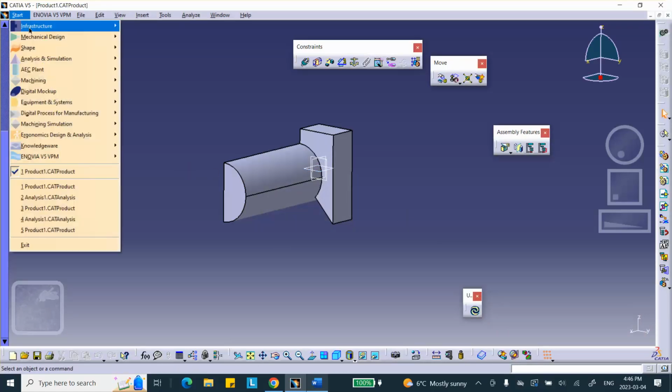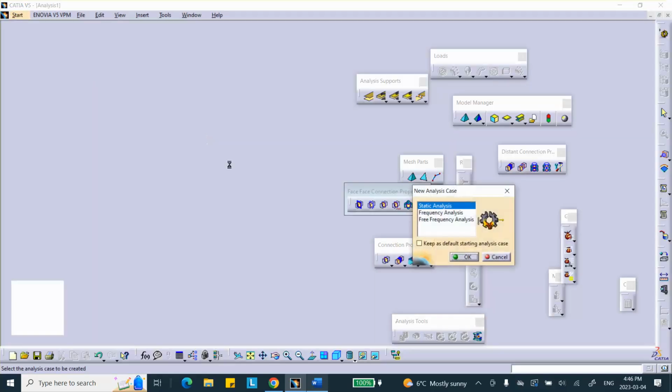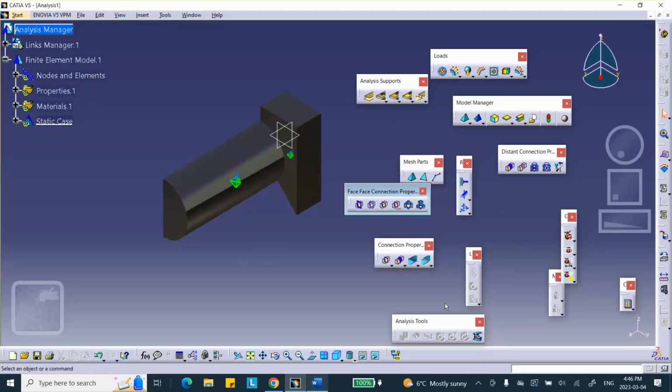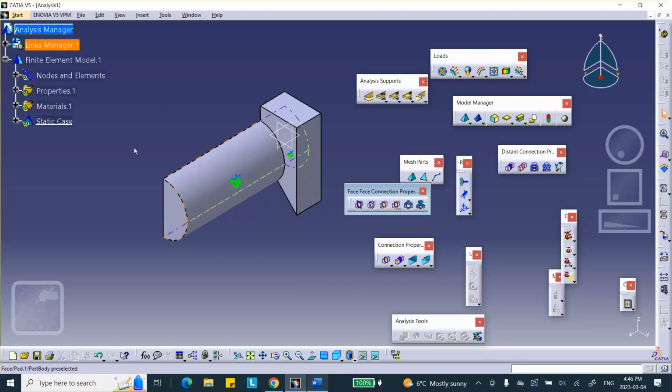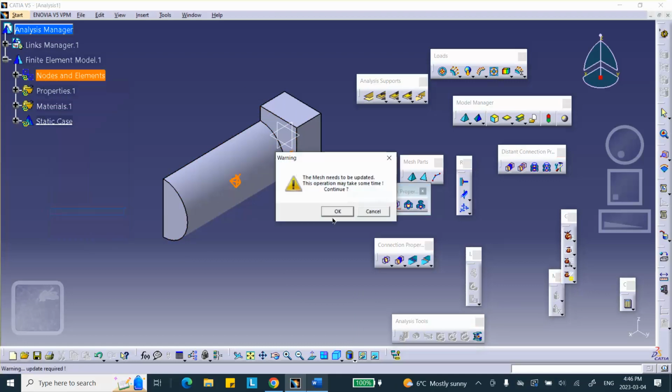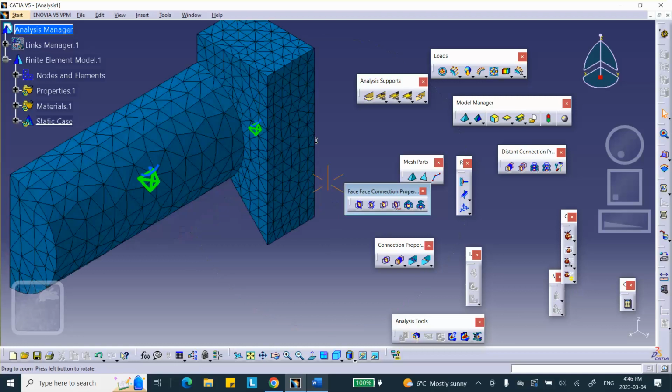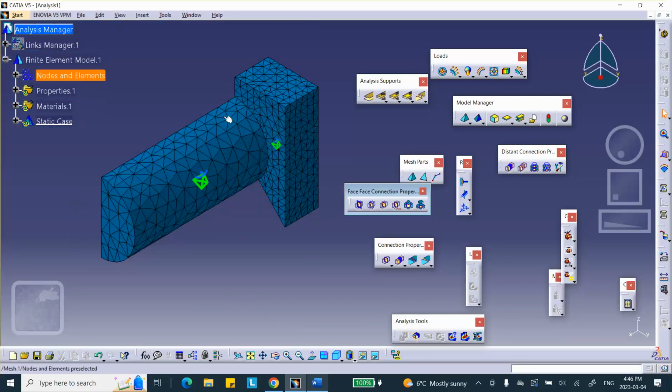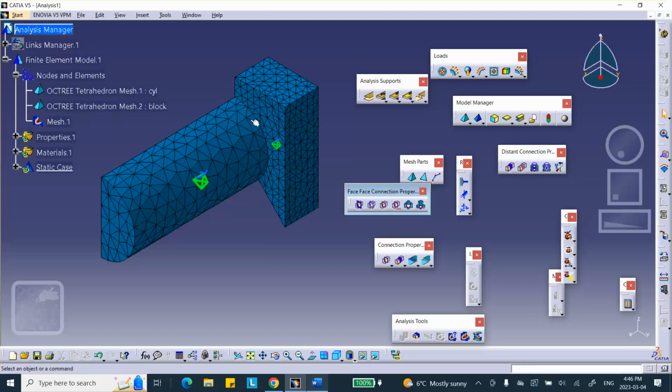So we're going to go to analysis and simulation, generative structure analysis. Okay, let me change the rendering here. There. Well, I'll keep the mesh the way it is. Right-click mesh visualization. You can see that. You know how to refine the mesh in an assembly and stuff like that. I've done it twice already in both activities in Lab 8, and you should be able to refine any one of these pieces or the meshes for any one of these pieces wherever you're asked to do that.